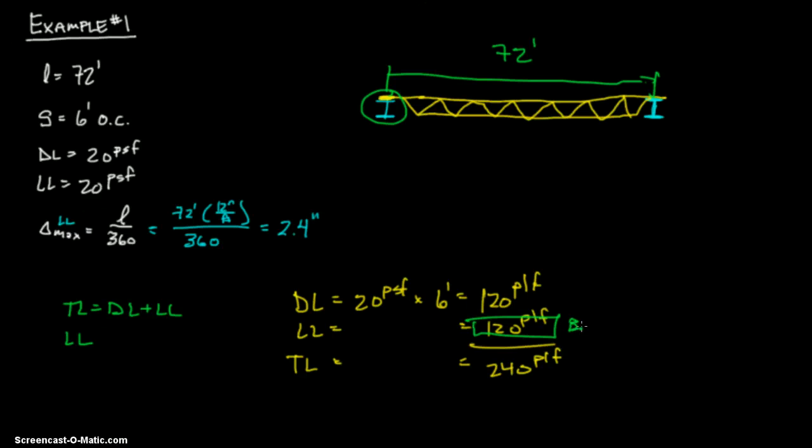This is our bottom. This is our top. Alright, so we want to go find minimum of 240. So let's start on the top. It looks like they are 36s. And that's the height of the joist. And we'll go over to 72, our clear span. And we want to go down. They've actually circled them in this. Makes it easy for you.